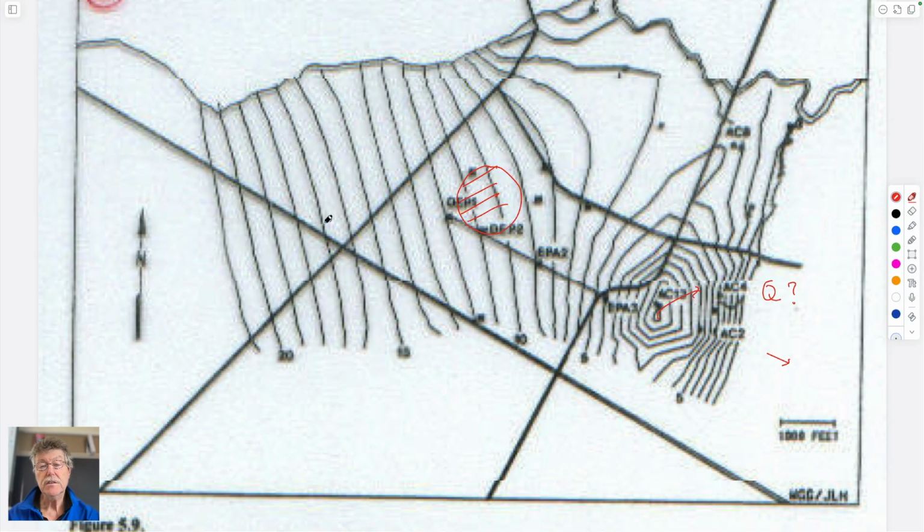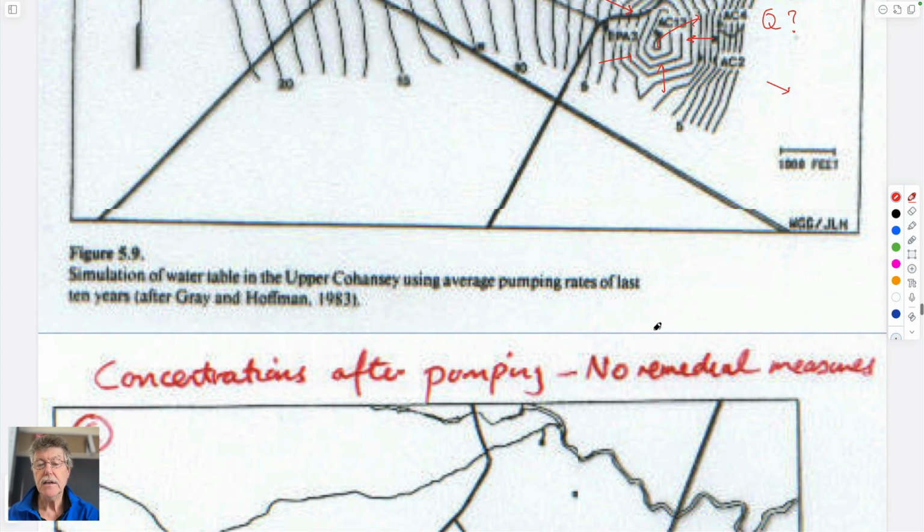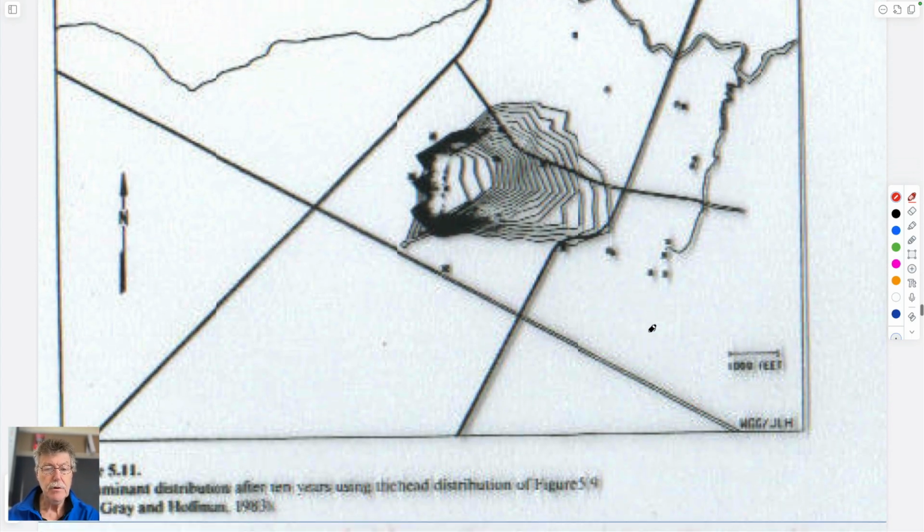So this would be just the equipotentials. So this means that water would be flowing perpendicular to these. This would be the Darcy velocity and also the advective velocity. And it doesn't really matter so much, but if you pump water out, this means that if it's coming in perpendicular to the contours on this side, perpendicular to contours on this side, it's not going anywhere. It's getting into a gravity well, basically, or a real well, actually, if you do that. So that's kind of the idea. And so you can look to see what happens here.